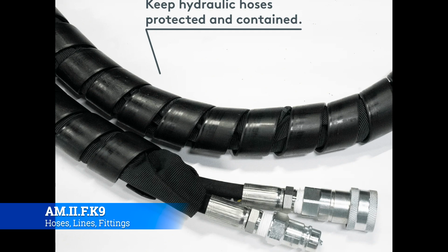One of the big moments that turned me away from this is that we had a hose bust in Iraq that about caused us to lose an aircraft. Several months into that rotation, we realized that we had fixed a lot of hoses, and we shouldn't have seen another hose bust like that, because we had gone through and really gone hard at making sure all of our hoses were taken care of, especially in the hydraulic system.